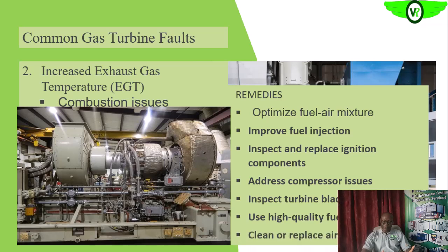Then the fuel also, we want to ensure that the fuel meets the quality standard that is recommended for the operations of that particular gas turbine. So if it meets it, we will not have much of a problem in the area of the fuel. Then we want to have a regular maintenance schedule for the air filter, the intake air filter, and also the fuel filter that is in the fuel system.